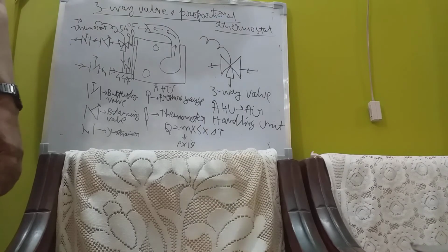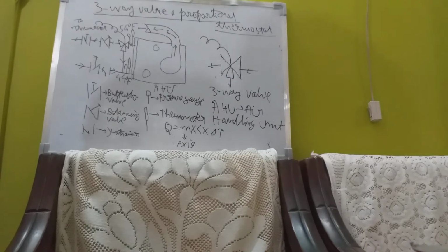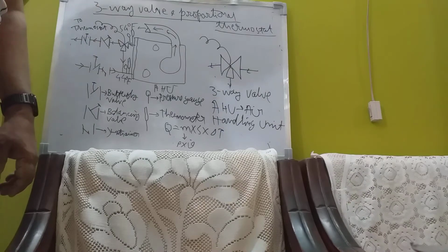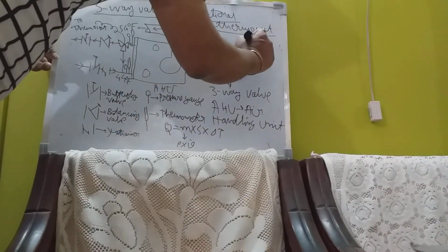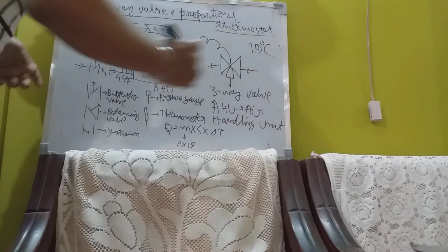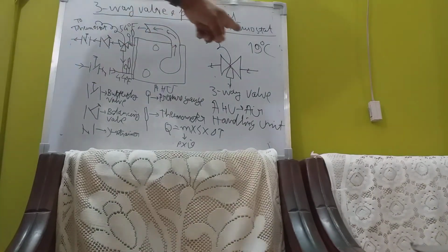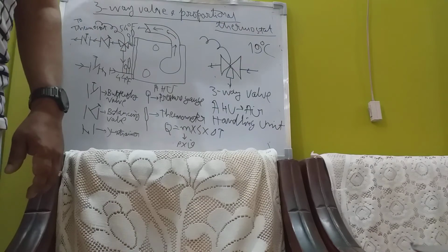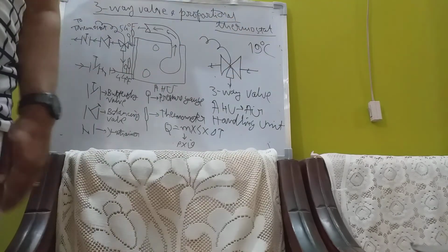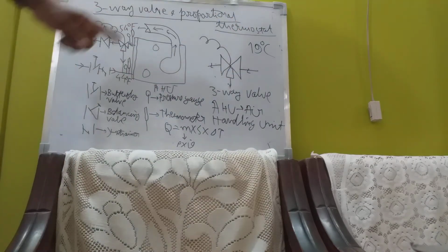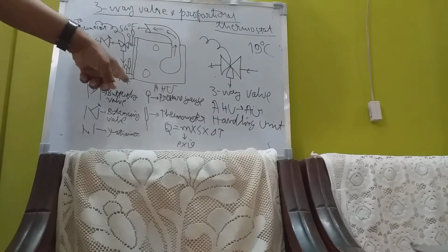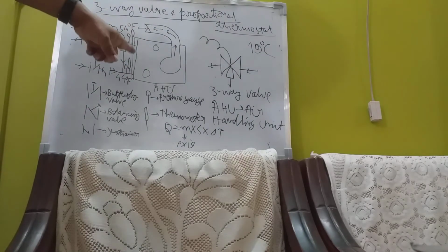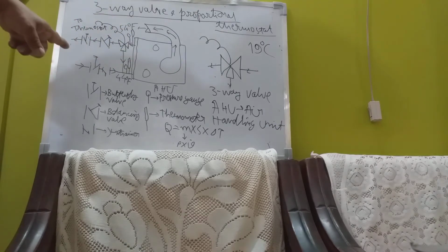And you, as an air conditioning engineer, HVAC engineer, have signed a contract with the client that you will maintain a particular temperature, say 19 degrees centigrade, in the room throughout the season. And it cannot be 20 degrees centigrade. If you have given a contract, he may go to court for that. So to maintain 19 degrees centigrade, you must have 44 degrees Fahrenheit water coming in. And it will be heated to 54 degrees Fahrenheit and going to the chilling machine.